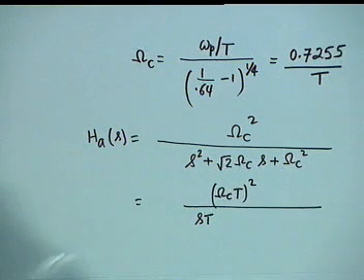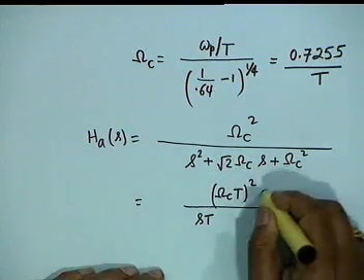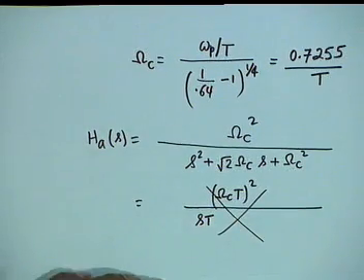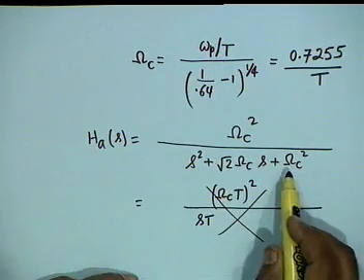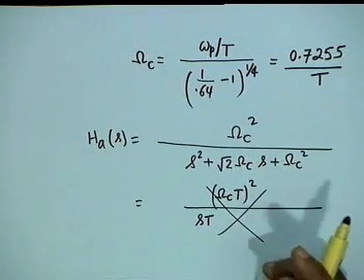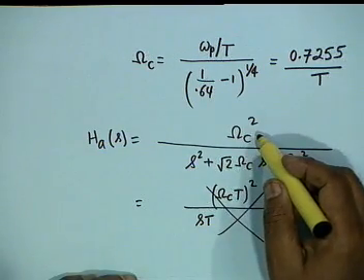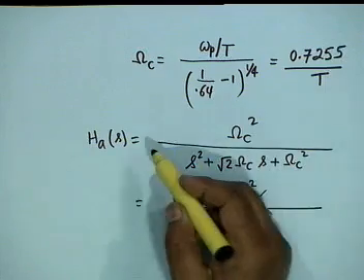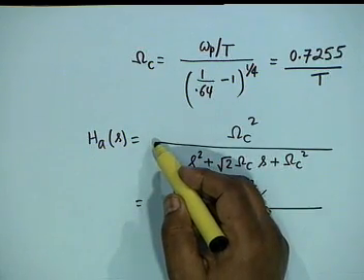Shall we write like this? Inertia. We are not doing bilinear transformation, so this is not needed. What we have to do is to decompose the denominator into s plus a whole squared plus b squared. Then the numerator is a constant. We have to adjust this constant to be equal to b. So multiply this by a constant. All right.